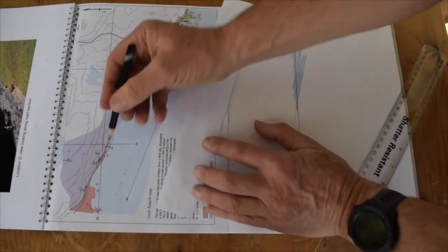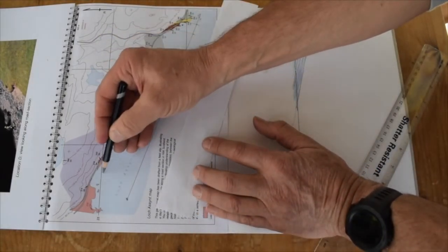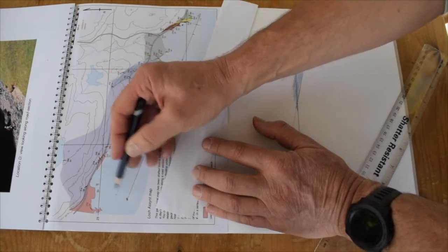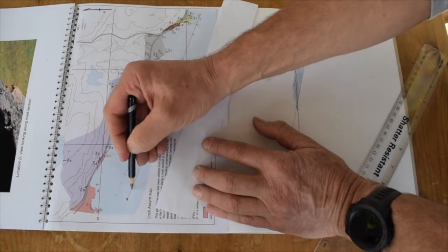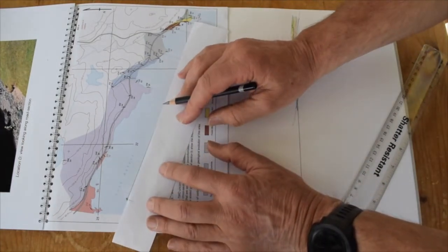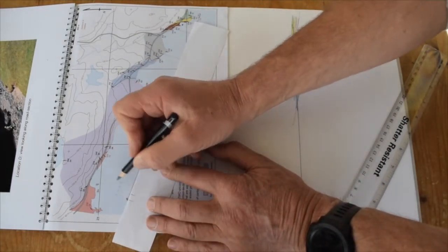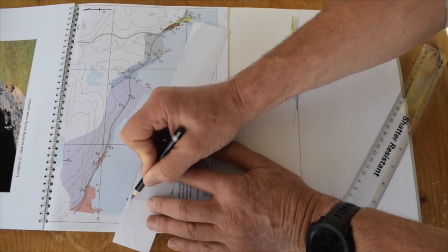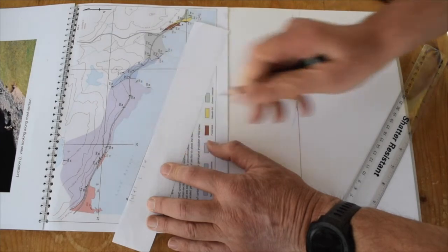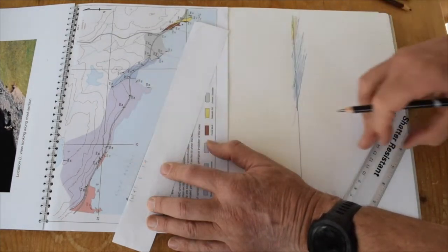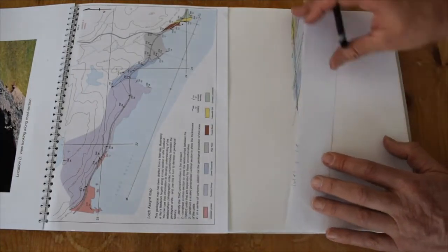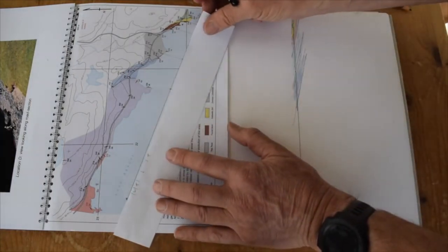But I'm just going to suggest that these undulations trend in this sort of shape through here, so we can just project them in like this. It'll get an idea of the scale, certainly. So again, I'm starting a new map strip. Let's line that reference point up to here. That bit there is Torridonian, that bit is Lewisian, that bit is Lewisian, that bit is Torridonian. So now I'm going to take that information onto our profile.